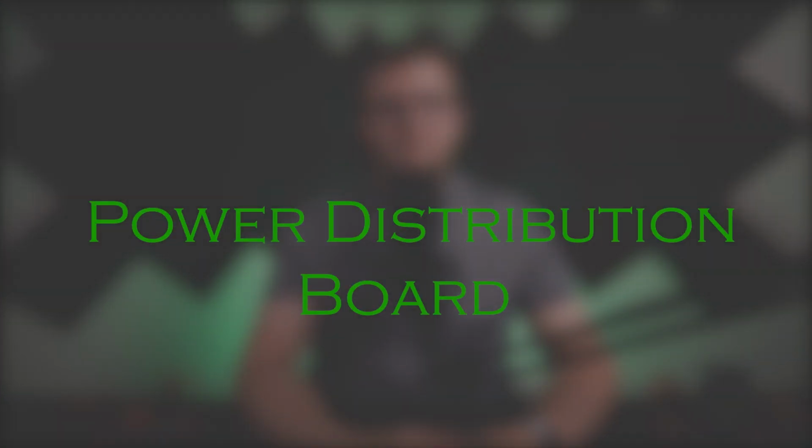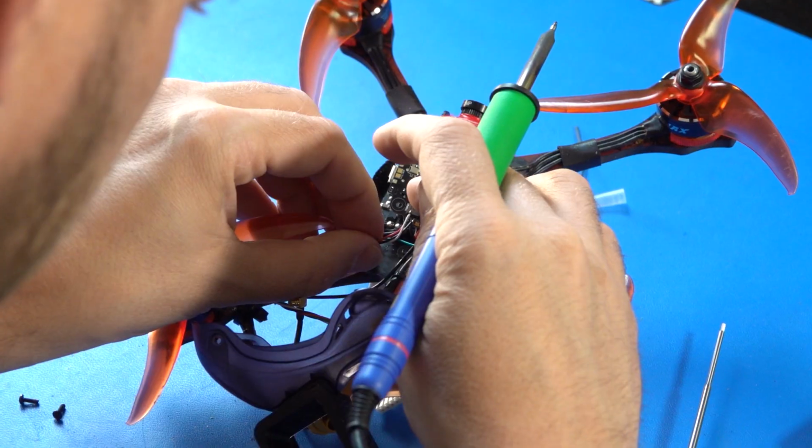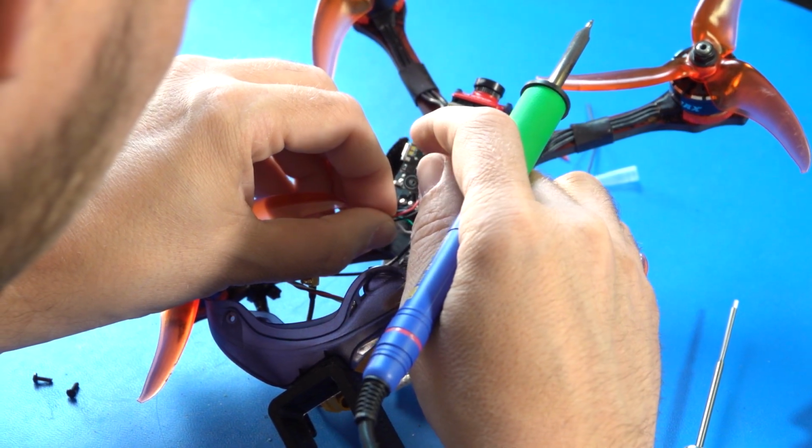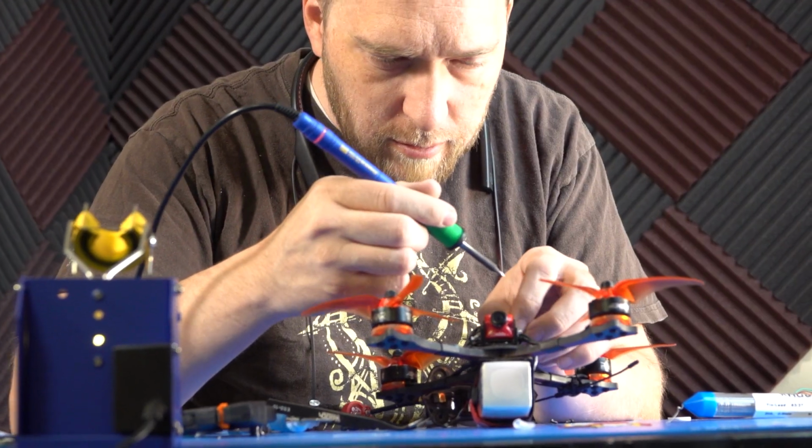Power distribution board. Like we mentioned in our video about power distribution boards, or PDBs, most flight controllers can now offer that system already integrated. If the flight controller you have or are looking to purchase has solder pads for electronic speed controllers, you can assume there is some form of integrated PDB.